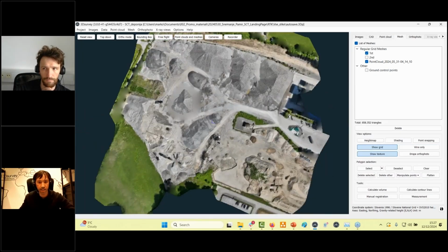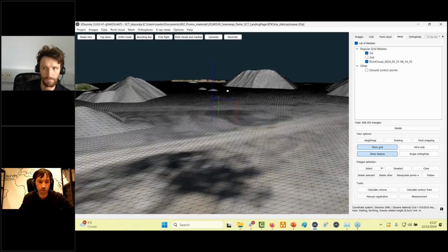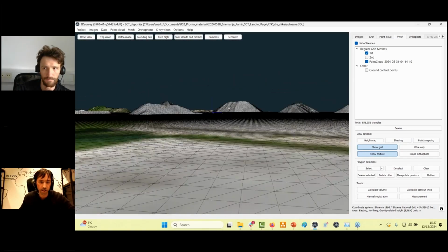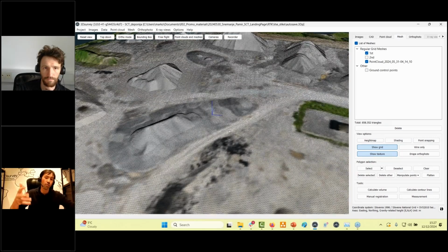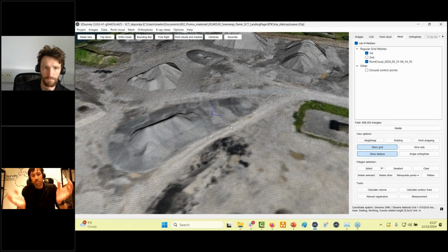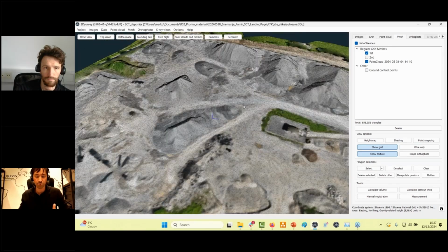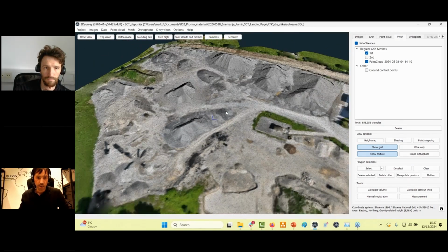So I have some plane which is cutting off my surface, as you can see here, and I can calculate the free volume, how much material you can put in some stockpile or hole or anything like that. Okay, I'm a bit rushing because of the long time.